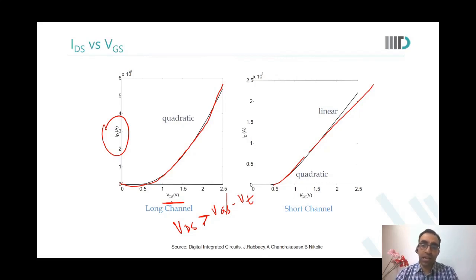In advanced technologies, we are integrating more devices onto the same die, and each of those devices is also leaking more because of advanced technology nodes. For low power and portable devices, leakage is a major issue. So we have many schemes, as we will look at later in the course, to reduce leakage. Leakage recovery is a special task done when you design chips. Some kind of implants and all; you will see that in VLSI.